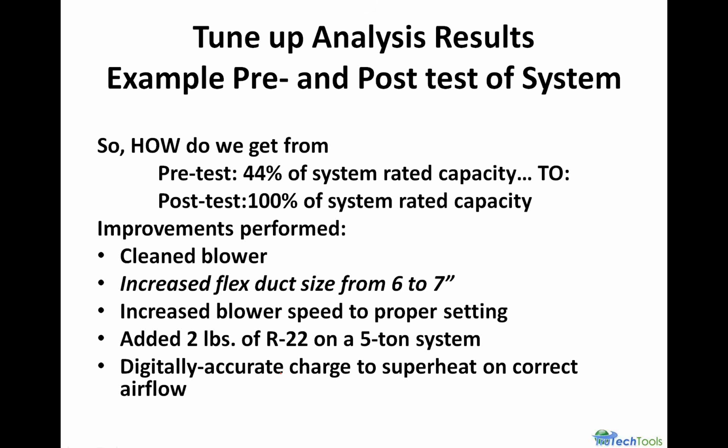Is this the way I'd like to see it? Absolutely not, because I've got an evaporator that's on the highest speed that it can be. It's working as hard as it can, and it's eating up some wear on the equipment simply because the duct system's not designed properly. However, this is a huge, huge improvement. We're getting now twice the amount of cooling out of that system. And is it perfect? No. Is it working much, much better than it did before? Absolutely. And obviously we had to add some refrigerant to it to get the charge correct.